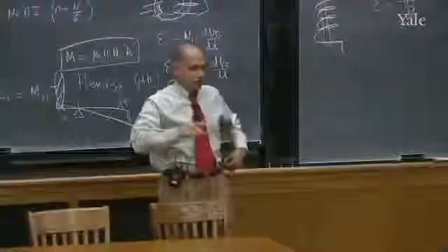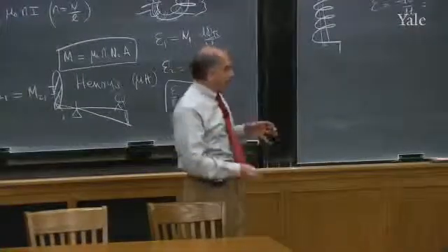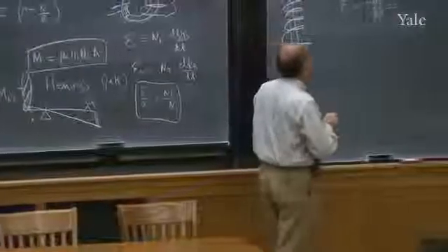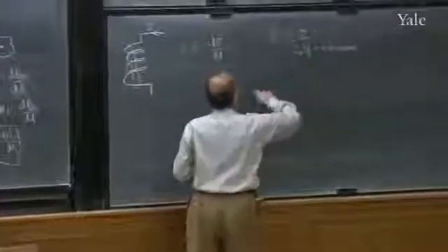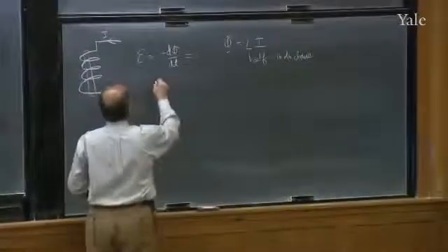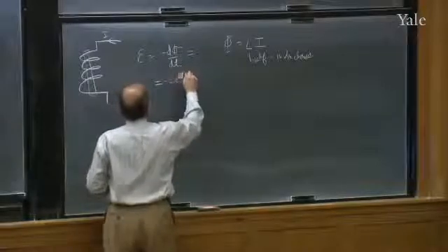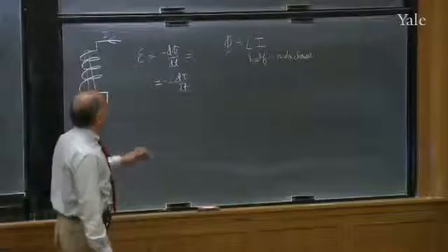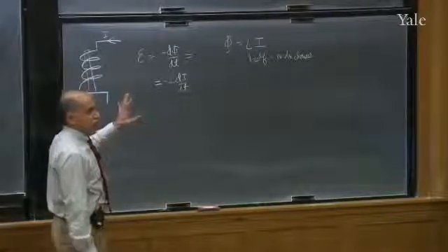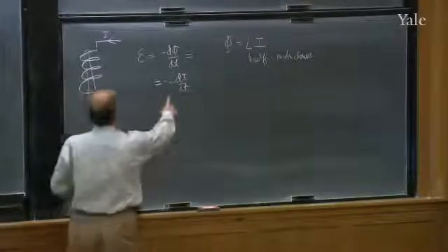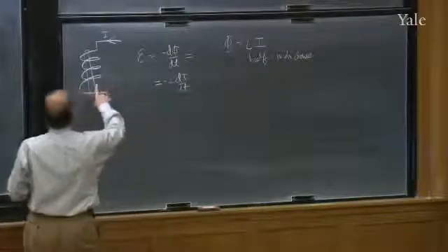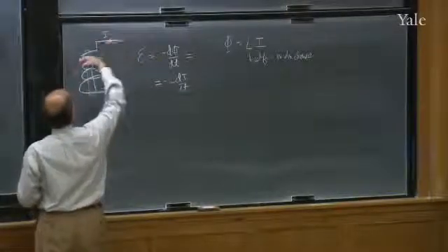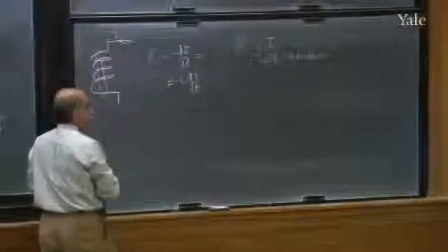So every coil, when it carries current, will have some flux threading through itself. So that ratio is called the self-inductance, also measured in henries. So this becomes minus L di/dt. We will calculate L in a moment, but I'm just telling you that as long as di/dt is not 0, you will have to oppose the back EMF with a voltage from some other supply.